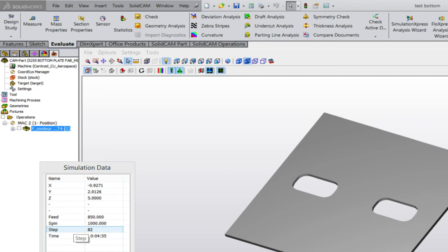That's not the case. You will be changing the tools. So how would the program know how long it takes you to change a tool? It could be 20 seconds. It could be a half hour if you were at class, right? Or an hour. So it doesn't know that. So this is only an approximate. But they're fairly good. It's actually a program of 3 hours. That's right. And you will end up doing that, especially in 3D surfacing, which we'll go into next week. It's going to be very important to change parameters around to reduce your time, because you'll end up making 10-hour programs. Okay, great question.